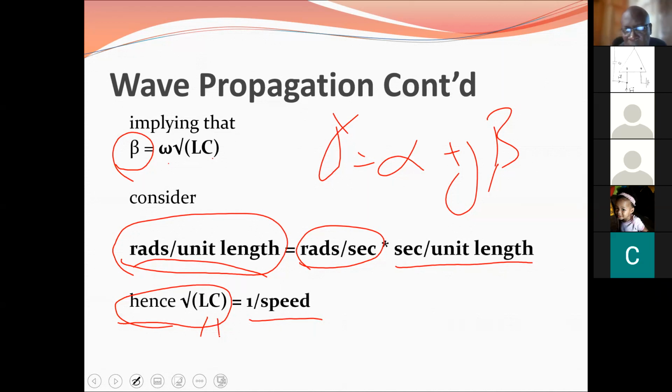So the type of insulation you use is dictated by the voltage that you are working with. So if you look on your sheath cable, for example, you will see it marked 500 volts or whatever it is set up for. What they are saying is that this cable must not be used on systems greater than 500 volts. Why? Because the insulation is what dictates that.